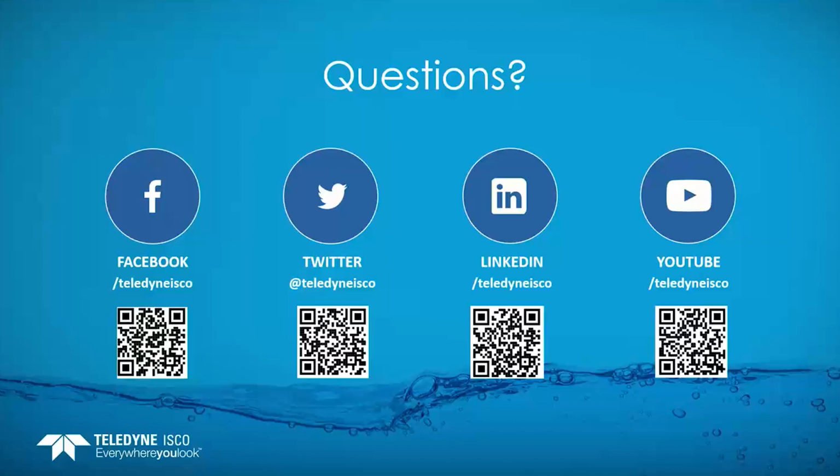Okay, let's see here. Here's a last question that's come in. I do not have the full recommended approach for the flume size I need. What are the options? Yeah, so we see this a lot in maybe an expansion of a treatment plant or a new plant where you just have limited options as far as your property or your easement. And the answer is the full recommended straight run into the flume is just a recommendation. If you can get things to be subcritical and uniformly distributed, then you're going to be fine. You can use different things like baffles, like I said earlier, to slow things down, and a few other design tricks in order to get that length that you're going to need.